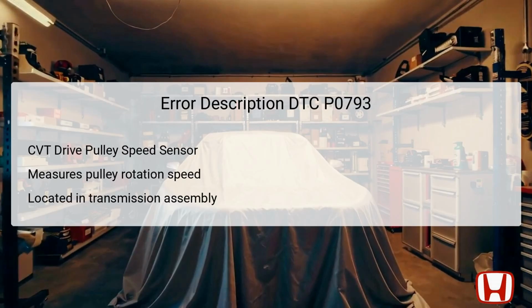The DTC P0793 code specifically relates to the CVT drive pulley speed sensor, which plays a pivotal role in the vehicle's transmission system. This sensor measures the speed at which the CVT drive pulley is rotating, allowing the TCM to adjust the transmission performance based on the vehicle's current needs.